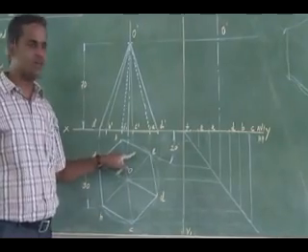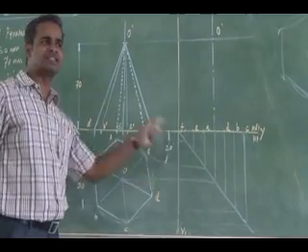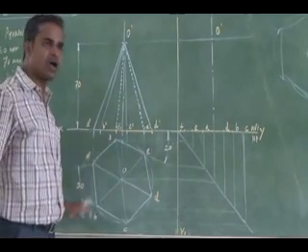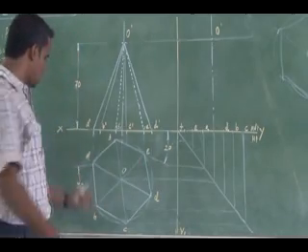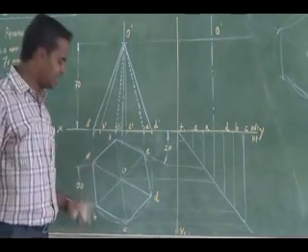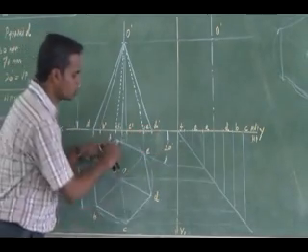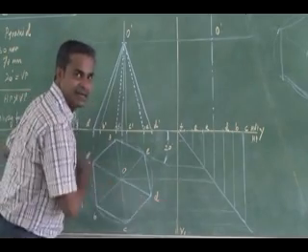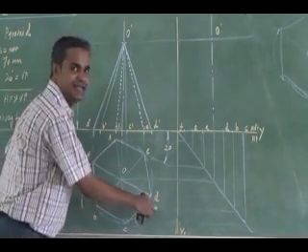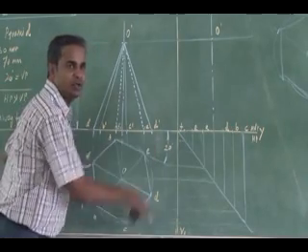Draw the base, with one of the sides 20 degree inclined. You will be drawing by the circle method. Draw a construction circle of radius equal to the side, 30 mm. Since one of the sides is 20 degree inclined, I can divide this circle to get corners A and D such that the line is 20 degree inclined to the reference line.